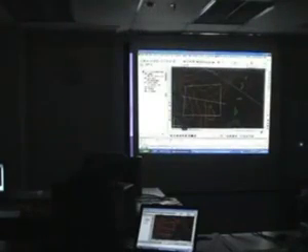So now we're going to run the volume calculations. In Land Desktop, we have 3 methods of volume calculations. One is the grid method, which is the normal manual method a lot of people use. They basically divide the drawing into grids, so the grid size, of course, is totally up to them. What they do is take the difference in elevation of each corner, take the average, multiply it by the area, and total everything up together. That's how we get the volume calculation using the grid method.